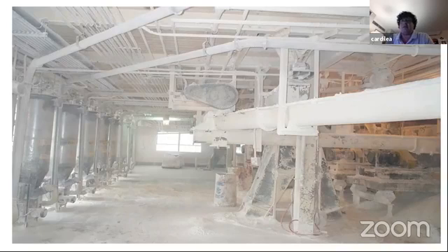And basically there's a couple ways they get the natural gas in there. One of the ways is they'll pull it off of tanker trucks. The other way is they'll pull natural gas in its gaseous form off of a pipeline and then put it through a really powerful compressor, using a variety of techniques, one of the 5 stages of compression, that pushes it together and turns it into a liquid. They get it to around -280 or so, and then they pipe it in.